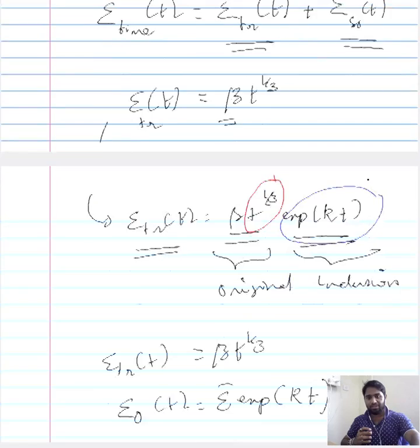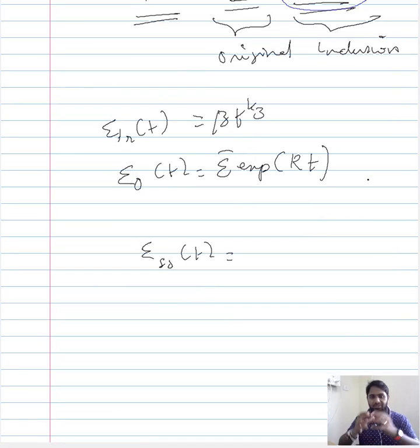So, assuming that even though you can arrive at and fit an expression differently, the slope is constant in the steady state condition and there is a constant that describes the change in state or change in strain for a definite period of time. When you multiply this constant with the time taken by the steady state creep, then this represents the overall steady state strain.